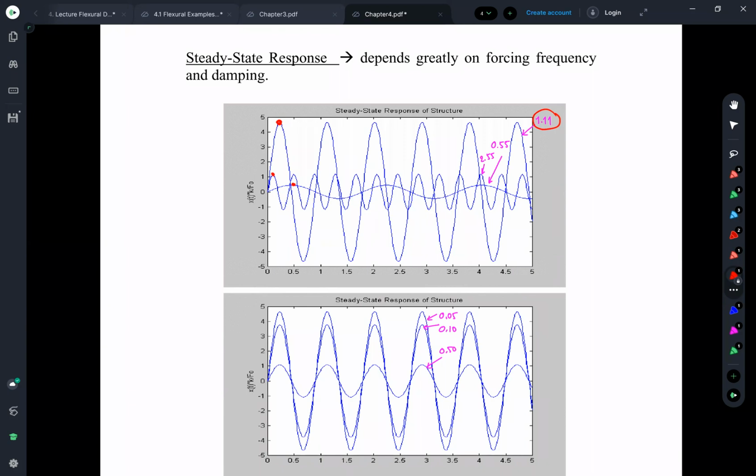Many design codes put the limit state design, ultimate strength design, the load factor that we often employ or adopt in many international design codes is between 1 point something, 1.2, until maybe 1.7, 1.8 at most. That is a safety on the loading.